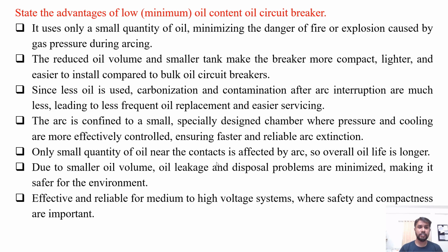State the advantages of low oil content circuit breaker. So it uses only a small quantity of oil, minimizing the danger of fire or explosion caused by the gas pressure during the arcing period. The reduced oil volume and smaller tank make the breaker more compact, lighter and easier to install compared to bulk oil circuit breakers. Since less oil is used, carbonization and contamination after the arc interruption are much less, leading to less frequent oil replacement and easier servicing.